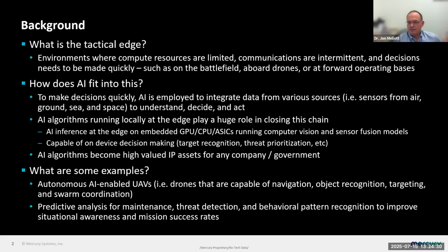I saw a demo at an academic conference just six months ago, on an ADAS system, a self-driving vehicle application, where someone was able, with a pulsed laser shining at a camera, to induce effects that would cause the vehicle to, say, turn in a controlled way. I mean, literally taking over the operation of the vehicle by what it was feeding into the inputs of the AI system.